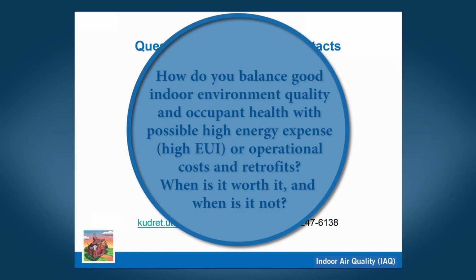So how I would frame it is, if you do a CO2 survey and there's a lot of numbers that are above 1,000 parts per million, somebody needs to do some long-term planning of how to come up with the capital to move the school into a modern era of providing reasonable ventilation for healthy occupancy.